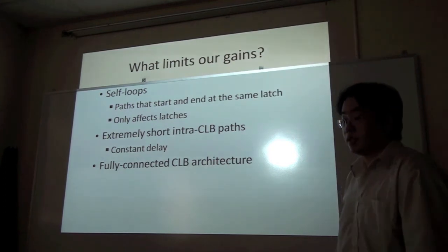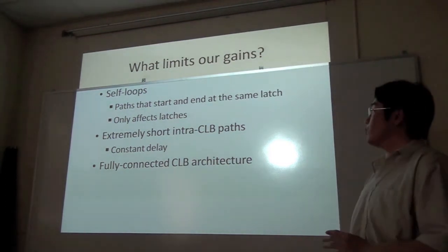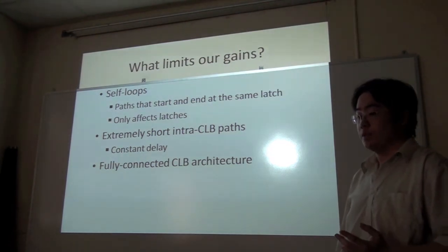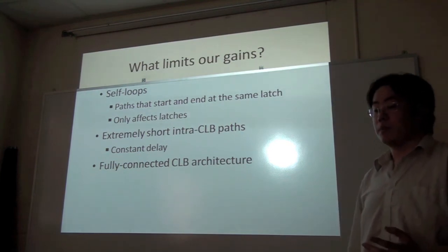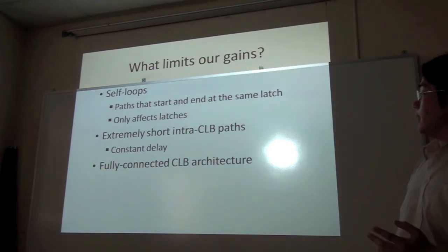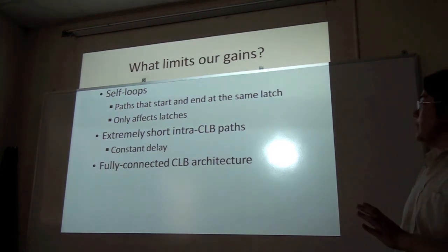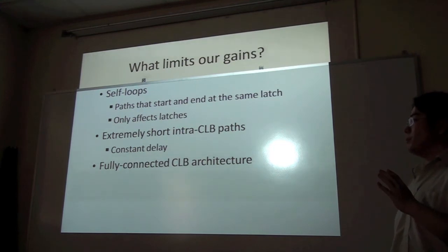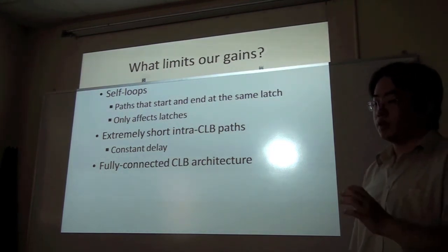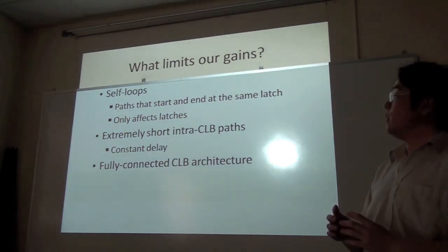Another case that affects clock skew and pulse latches is the extremely short intra-CLB paths between registers, and currently VPR models them as a constant delay. And finally, the CLB is modeled as fully connected, meaning that you can go from any logic block to any other logic block within constant delay.